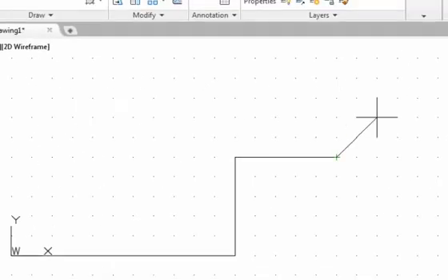As you have seen for the 3 line segments we have created so far, we started with the absolute coordinates input method for the first line segment, and then we switched to using the relative coordinates input method for the second line segment, and for the third line segment we used the interactive input method. For the next line segment, we will use the relative coordinates input method again.